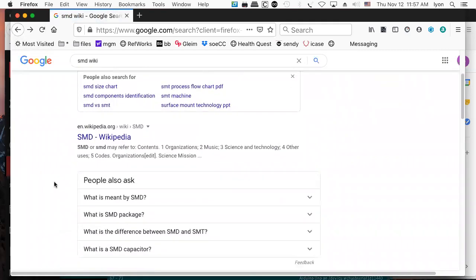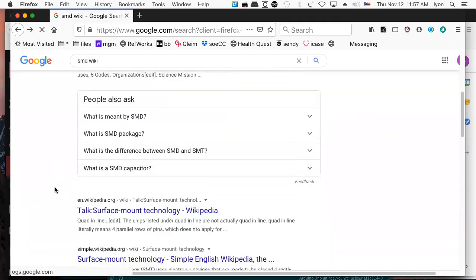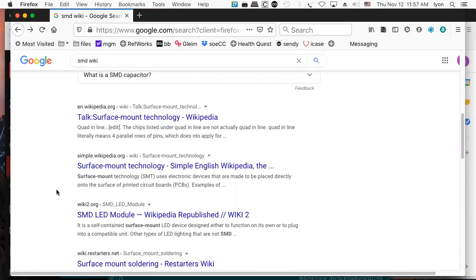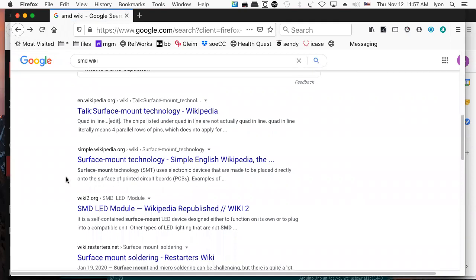We have a toaster in the stock room, which has been modified to be controlled by an Arduino and has a K-type temperature sensor in the back. So you can use that for surface mount. But also we have a full surface mount assembly line facility right next to the microscope. So with that, you don't actually have to use a toaster oven. You can just throw the boards on one end and they'll come out soldered out the other end.